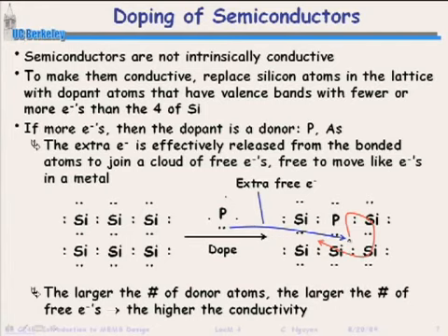And can you think of another material that has a lot of free electrons? Metals, yeah. What metals are, right, is a cloud of electrons free to move around that metal. That's why it's easy to pass current through the metal. That's why the metal is conductive. Well, if you think of it, by doping the silicon, you're basically making it a metal. You're creating a cloud of electrons that you can move back and forth with electric fields. These electrons are not really tied to these atoms. This is the simple hand-waving argument, right? If you're in a materials science class or other classes, you get much better arguments. But here, this is the best I'm going to do in the time that I have.